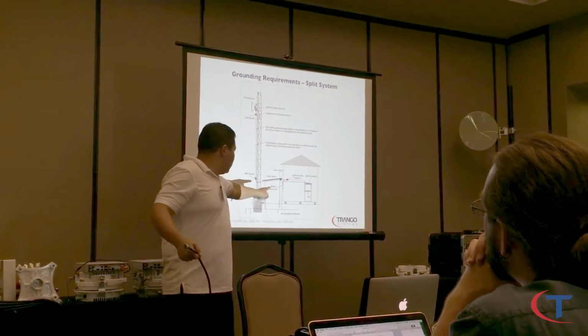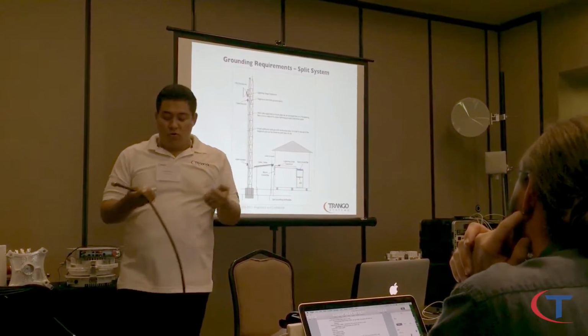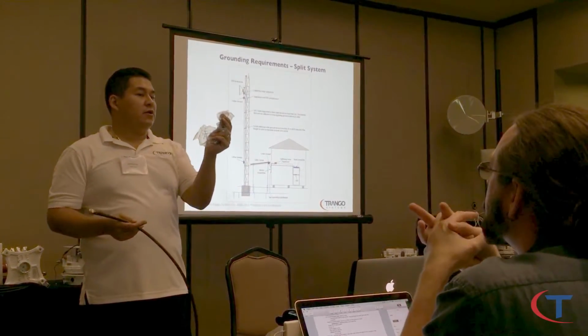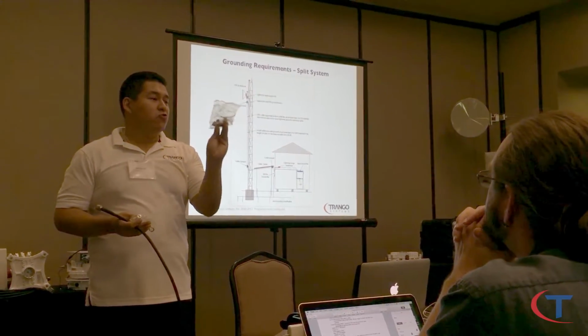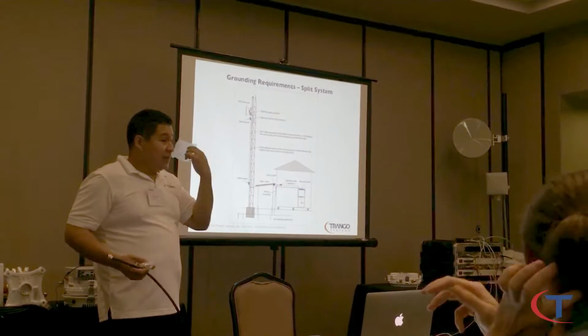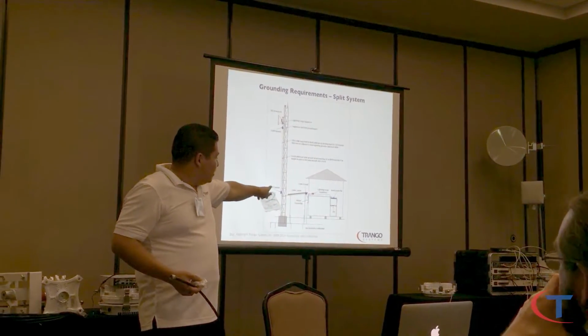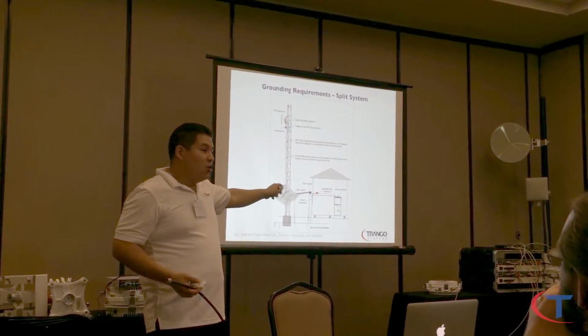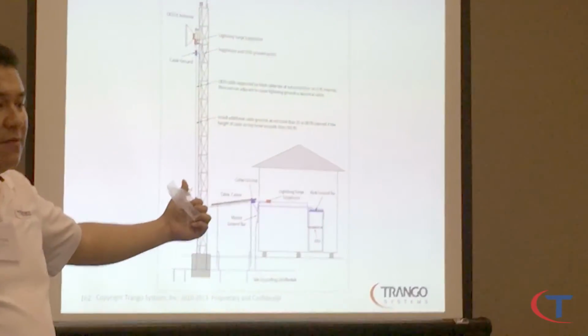This one here, lightning surge suppressor, is the other model. We have 2 models. One is for the ODU, directly connected. This is inline. So this goes before your rack. If you can put it outside, that'll be better. I mean, you want to keep the lightning outside. So it's before the rack. You want to protect all your valuables. You want to protect your Cisco switch, your IDU itself, anything that can get burned.